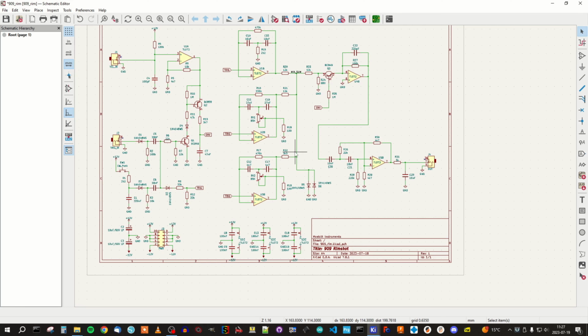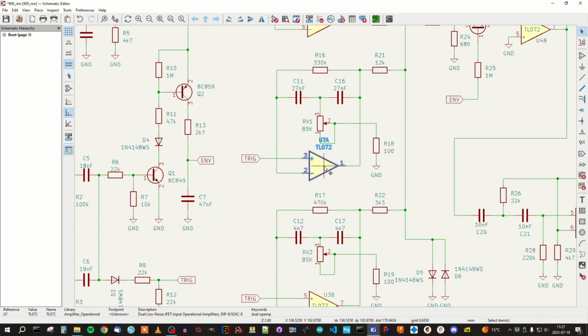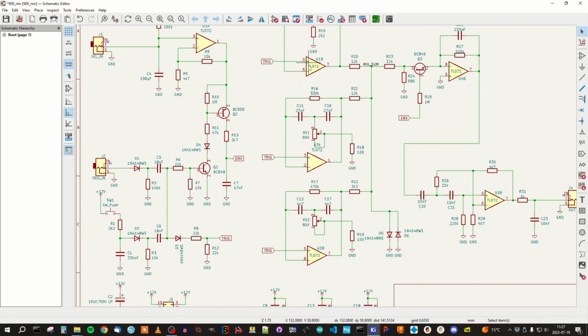So I will fix that, and I think these two could go together. So I will delete that, take a copy of that, and add it instead. Check that the plus and minus is correct. This is a very common mistake if you, for example, have an op-amp that is flipped and then you copy from somewhere else and put it there, and if you forget to flip it, then yeah, you can figure out the rest yourself.